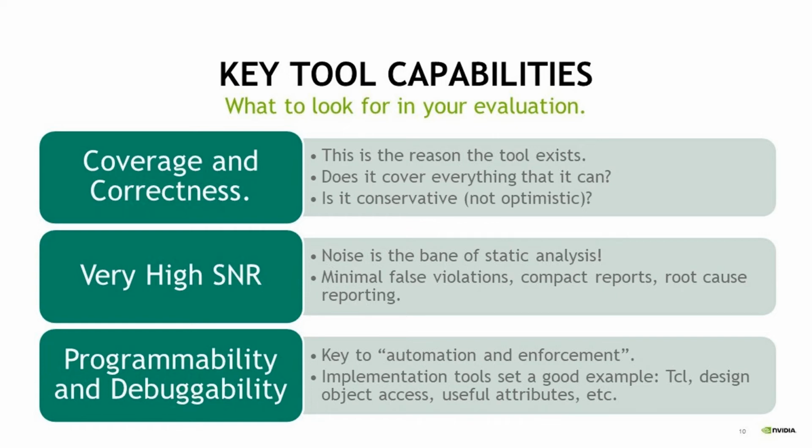Now, static sign-off tools are notorious for being noisy. They'll generate lots and lots of messages that are either incorrect or not of interest to the designer. So this is another area where tools differentiate from one another. You want a tool that doesn't generate a lot of false violations. You want a tool that generates compact reports. And ideally, you want a tool that focuses on the root cause of the problem rather than all of the myriad symptoms that are triggered by that root cause. So that's something to look at when you're comparing tools.